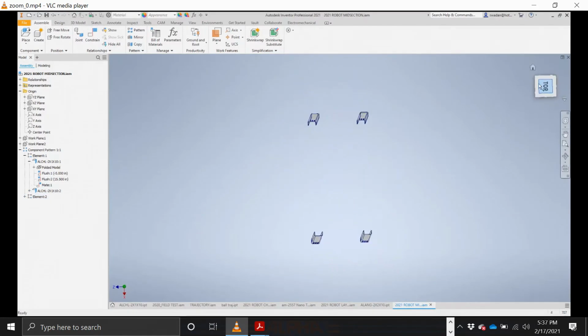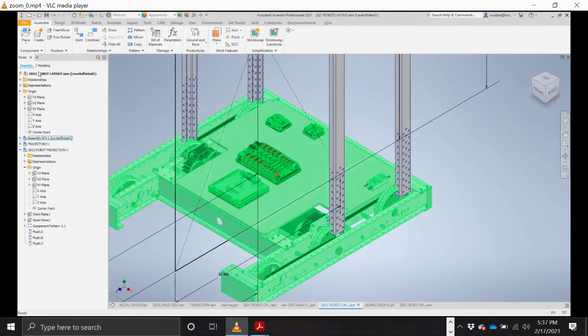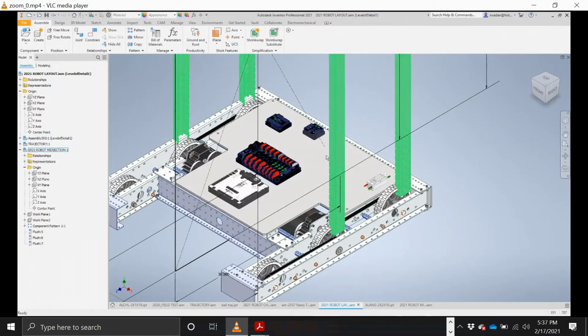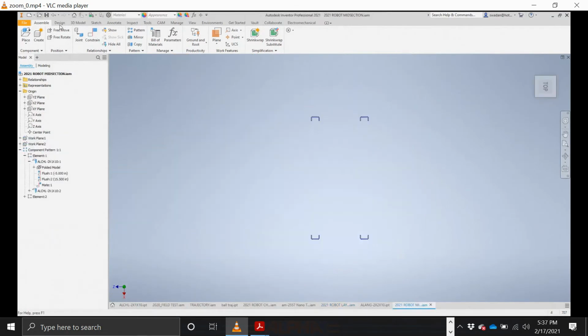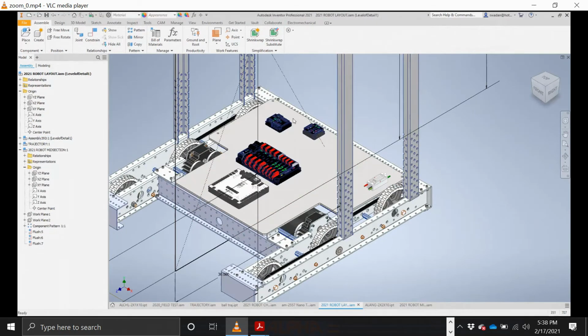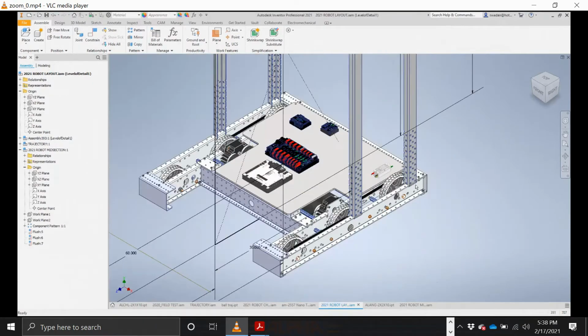And that'll change my mirror, and I need to, it didn't change, so I need to update it. Oh, but it only did one side. So I've got to go back into my second channel, and I have to do the same change with that mate. See, it recreated the mates because I told it to reuse the same components. So now I make that 15.5, and I go back and update, and now you can see it's pretty close.